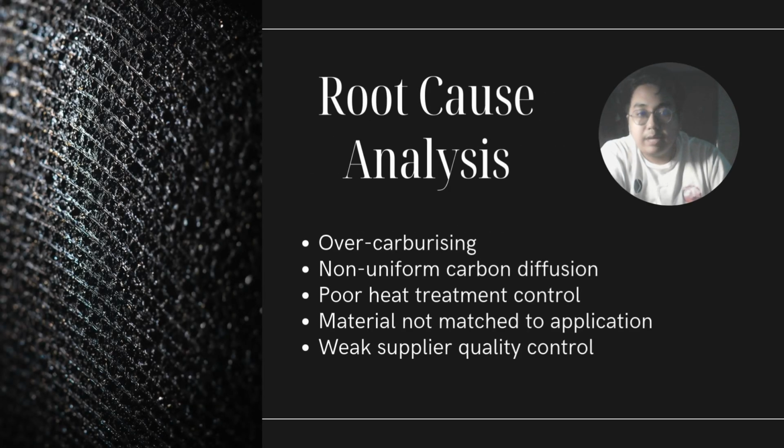From the correlation that I mentioned before, we identified several root causes. The main cause is improper carburizing, where the plates were over-carburized or exposed to a carbon-rich environment for too long. We also found non-uniform carbon diffusion, likely due to temperature or time inconsistency during the heat treatment. Other than that, poor cooling control may have introduced residual stress. And there might be some mismatch between the delivered steel condition and what the customer needs. Overall, all of these issues reflect very weak supplier quality control.